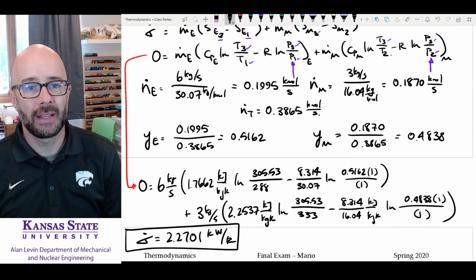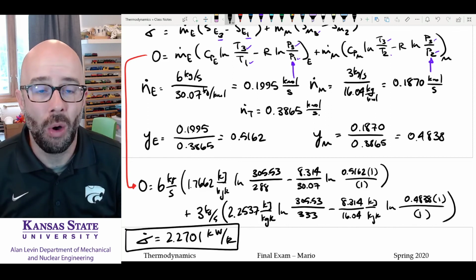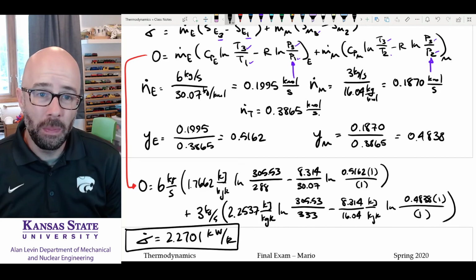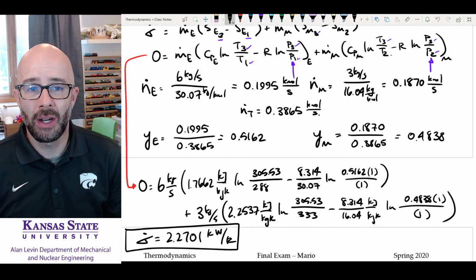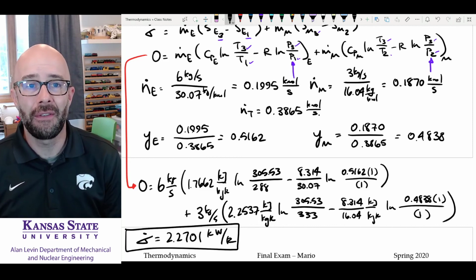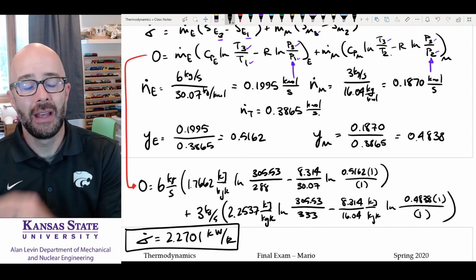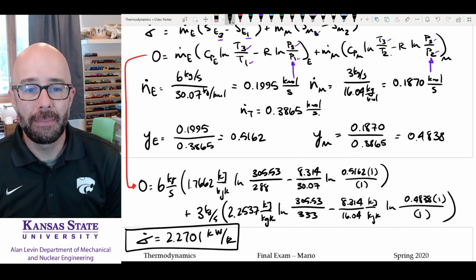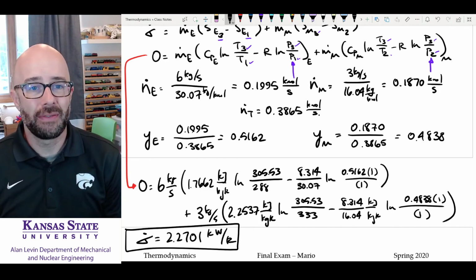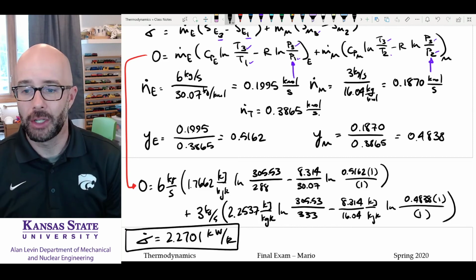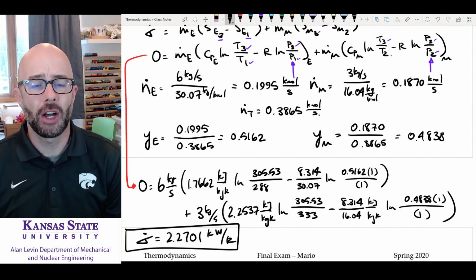These are all things I'm going to make sure you know when you talk about ideal gas mixtures. You're going to have either an open or closed system ideal gas mixture. I promise you there's going to be only 2 things mixing in it, not 3 or 4 or 5. You need to know about mole fraction, mass fraction, how all those equations work, and how you can manipulate them, and then you'll be fine on your ideal gas mixture problem. We'll stop there and move on to our next problem.